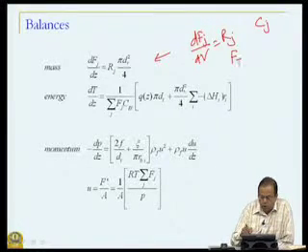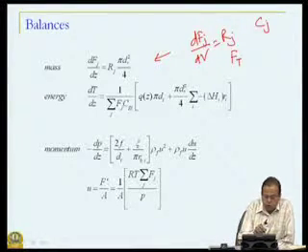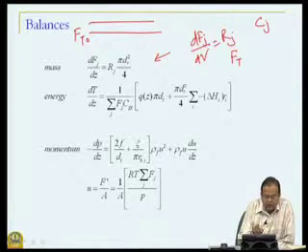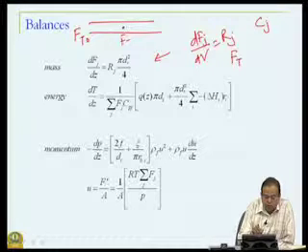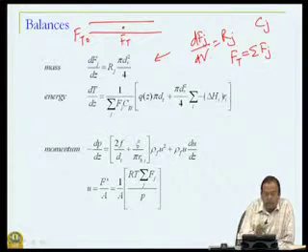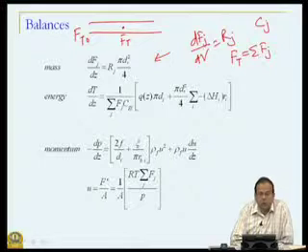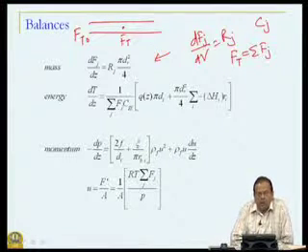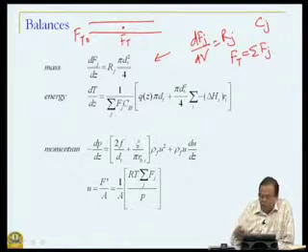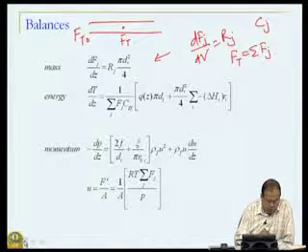So, Ft, for example, at any point of time, suppose you take this as a reactor and the total moles that are entering is Ft0 and at any point of time is Ft, then this Ft is not the same as Ft0. So, there is a change in number of moles, which results in a change in either the volumetric flow rate or change in concentration and so on. So, we deal with dFj/dV, which is equal to Rj.